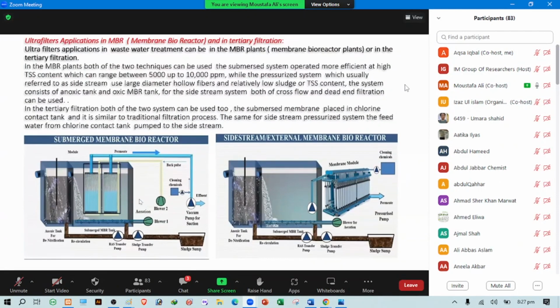In this process, as we see it here, I got your question, I will explain to you. We have this anoxic zone. It acts also as a clarifier. So we have sludge precipitating, and at the same time sludge returning to it to continue the degradation process.